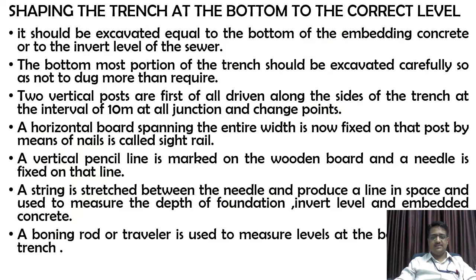Now, the next step of sewer laying is shaping the trench at the bottom to the correct level, because excavation is one part. Whenever you do this excavation practically, there will be a lot of rough edges that remain because of the practical difficulties. Now the next step will be to correct the level of the bottom. It should be excavated equal to the bottom of the embedding concrete or to the invert level of the sewer.